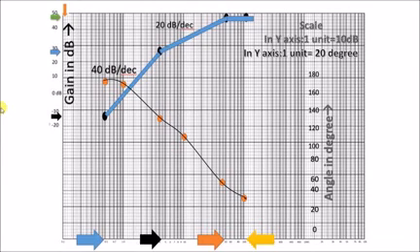This is a smooth line, not joined using a scale. The previous magnitude line should be joined using a scale, but this phase line should not. It is a freehand sketch. As the number of frequency terms increases, you will get a very smooth line. So this is all about drawing the Bode plot, and this is not over yet.